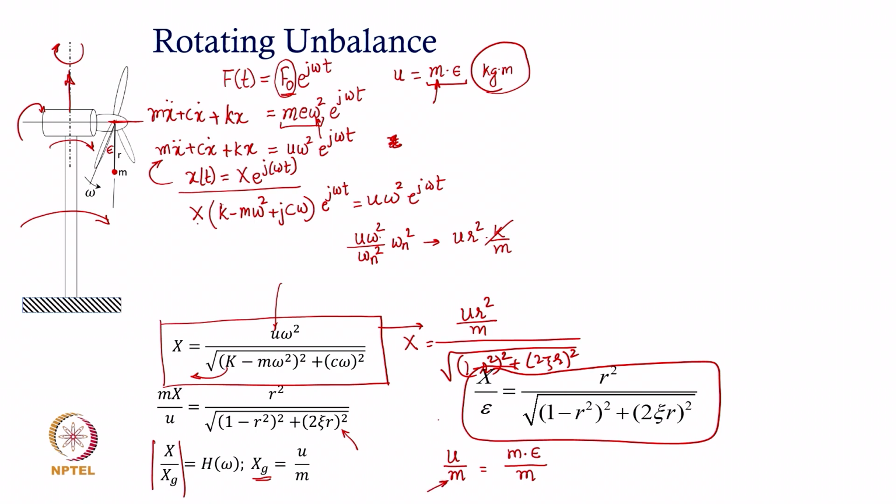So, in practice what we typically get by a measurement process is the total product. Okay. When you experimentally find the unbalance in a typical rotor system, you do not really get mass separated and eccentricity separated, you get basically the total unbalance in the system.